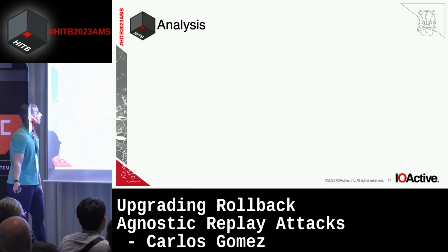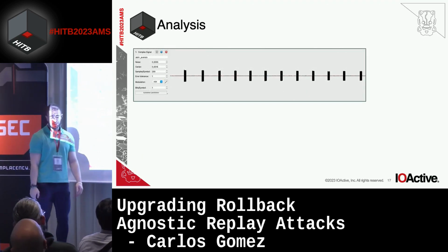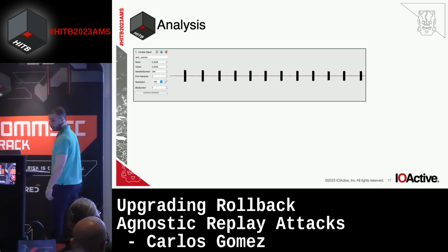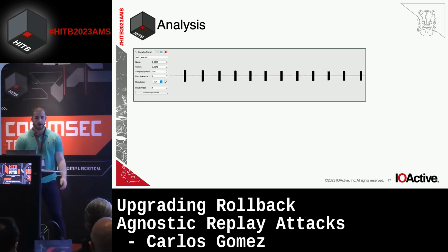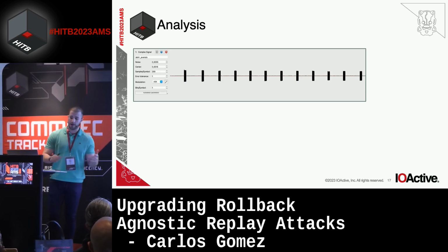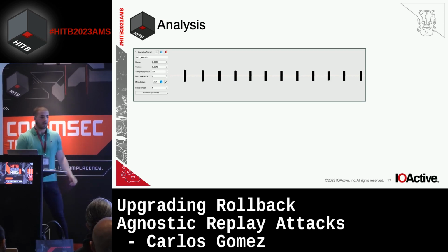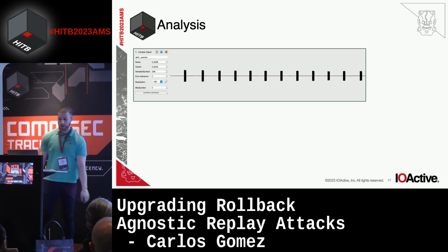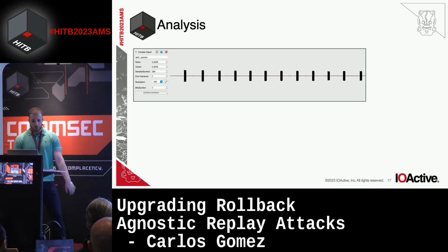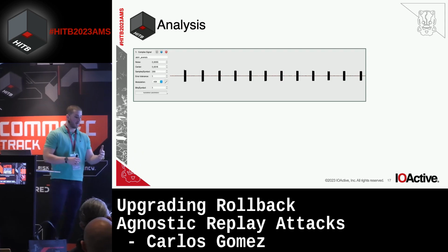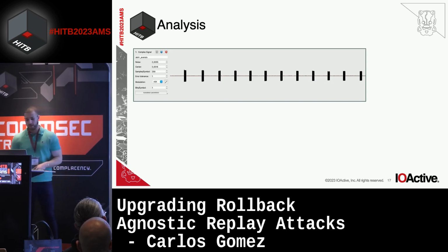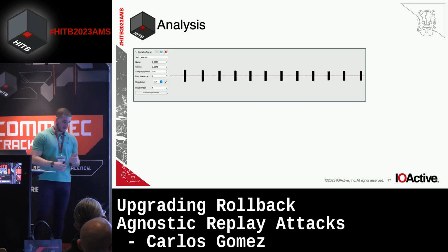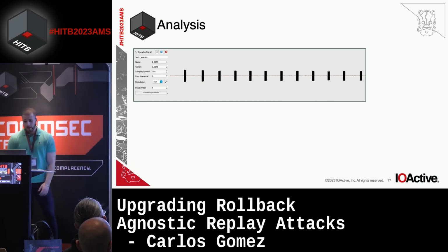And I put here a brief analysis about how you need to perform these techniques, because okay, everyone here likes to take your HackRF, send some signals, and open the car without the key fob. That's awesome, but it's really important to do this kind of analysis because it's important to know what hardware the key fob is using, which kind of modulation, and which kind of coding algorithm at the bit level.